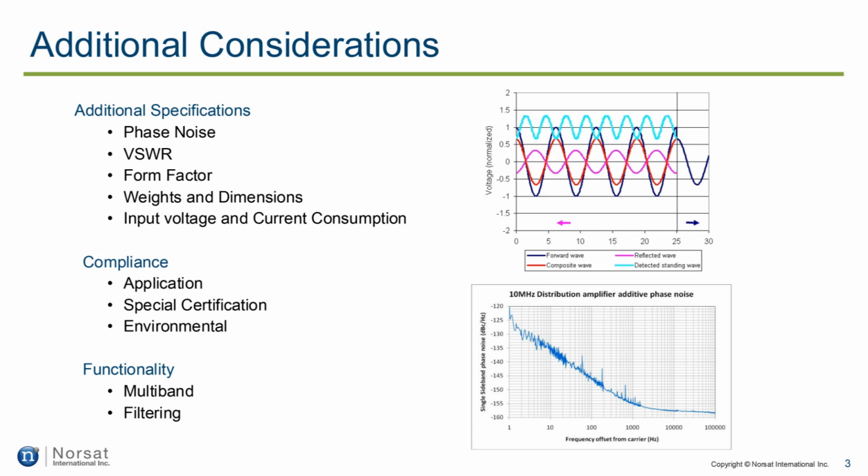The rest of the specifications may or may not significantly affect the system performance. Some applications might require considering them to ensure proper performance. One of them is phase noise, which is the noise introduced by the oscillator at various frequency distances on the converted signals. This can significantly impact the bit error rate, or BER, especially with more complex modulation schemes. The SWR is the efficiency of how a wave is properly inserted into a component of the transmission line. An inadequate coupling might cause reflections between components that can distort the original signal.